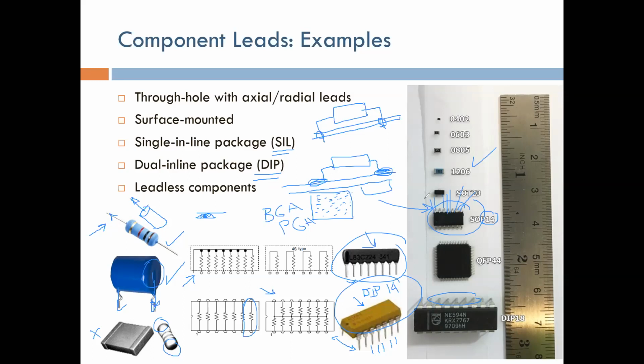And we ended up basically creating a printed circuit board that we solder this on, and then the printed circuit board is connected to wires or something like that, so that we can actually use these wires on a breadboard. So if you order a component that is not DIP, or not through-hole, you're going to have a lot of problems when you try to use it for prototyping on a breadboard.